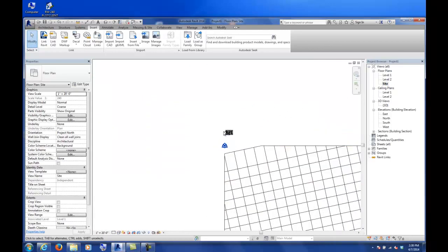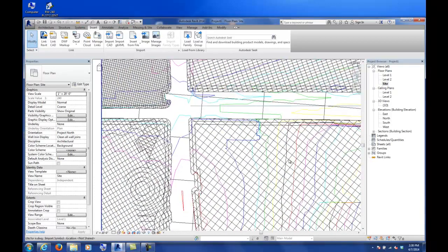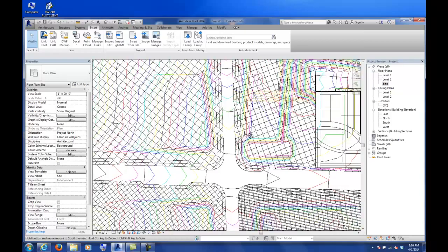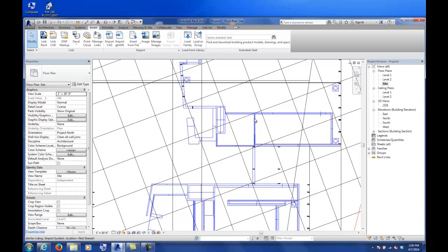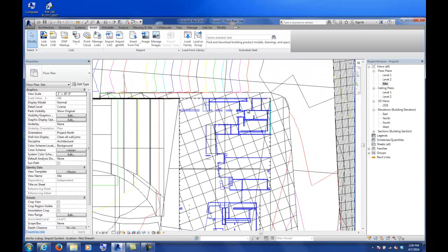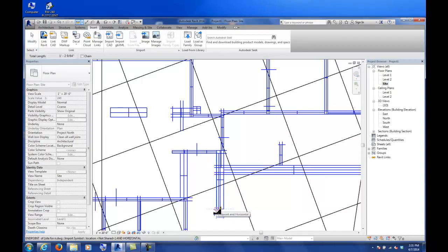But I probably shouldn't assume that. What is that? So one thing that you probably want to check is, looks like there's some floor plan information on here from something. So you would probably want to go back into the AutoCAD file and just verify that when I strike a dimension, and I'll do it from this line to here, that wherever you're striking a dimension, this happens to read 1 foot 2 and 9/64 of an inch. So I'm assuming this is probably scaled right if that was supposed to be a wall.